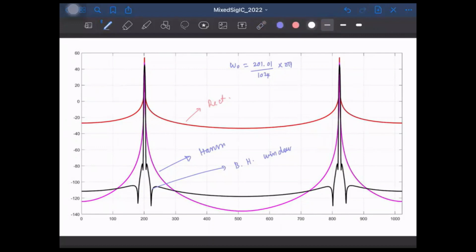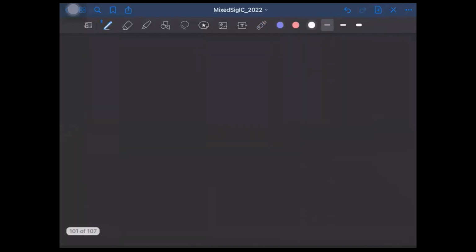So now we have discussed what happens when we take the discrete Fourier transform for the sinusoidal test signal, right? Let's see what happens to the spectrum of the quantization noise when we use the discrete Fourier transform. So for characterizing the ADC, we feed a sinusoidal signal of the form cos 2 pi times m by n into it, and we collect a total of n samples and take the discrete Fourier transform, right?